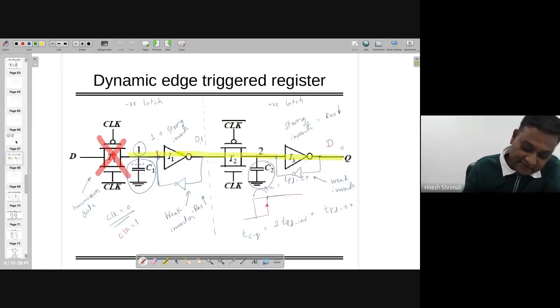So that capacitor has been kept over here. Just for simplicity, there is one capacitor, but you can take your own value also. But in that way, if you are increasing the capacitor, the required time to charge and discharge will decrease. You can understand that the combination of the resistance of the transmission gate and the capacitance of this one is going to decide how much propagation delay will be there.